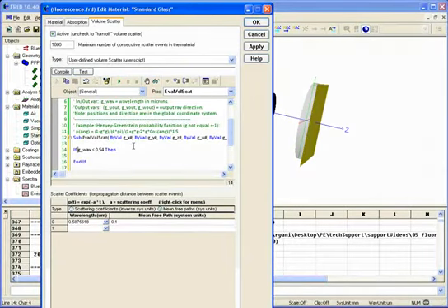Because the ray coming in to this system, remember, it's a blue LED, so the wavelengths are going to be less than 0.54 microns if they have not scattered yet. Once they have scattered, their wavelength is probably going to be changed in the fluorescence, so we don't want to go through this whole process again. So we're just going to scatter the one time for wavelengths less than 0.54 microns.